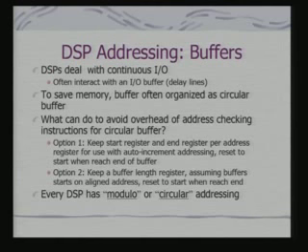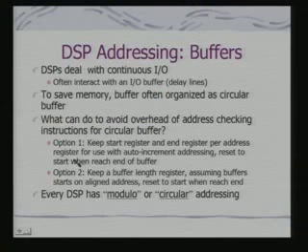So, that is why we say that each DSP has modulo or circular addressing. This is a distinct feature of the addressing modes of the DSPs. You will not find this kind of modulo or circular addressing mode available with general purpose processors, and this is implemented through these kind of options, either having start and end register or having a start and a length register. And all checks here for implementation of circular addressing are implemented in hardware.